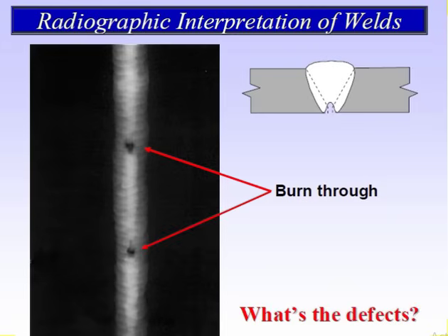And if you see in the image, this is the portion, you see the black in the circle. This is a circle and you can see the black hole like this. So this is the burnthrough. Burnthrough is very important, everybody knows, those working as the welding inspector, welder or welding supervisor. Excessive current is supplied to the electrode, so the amperage will be more, then burnthrough will happen in the joint.